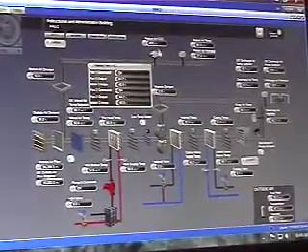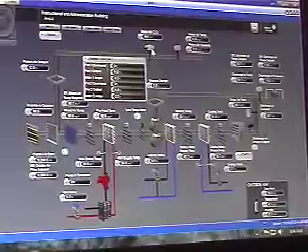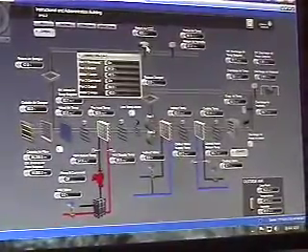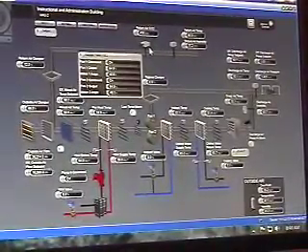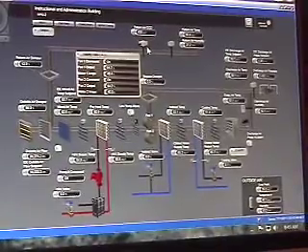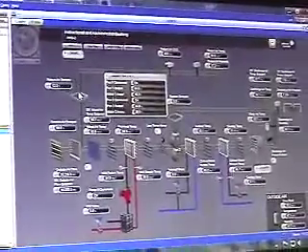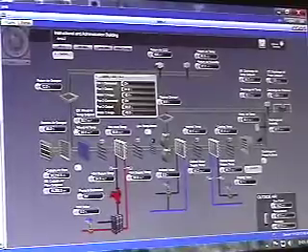Keep going down here, you have your return air CO2. Return air CO2, that has the ability, if your return air CO2 gets above, I believe, 800, we will slowly start resetting our minimum outside air flow set point up. I believe it resets it in 10% increments until it eventually gets to the maximum set point. So if your return air CO2 gets too high, you will have a potential to reset that maximum outside air to 100% outside air.